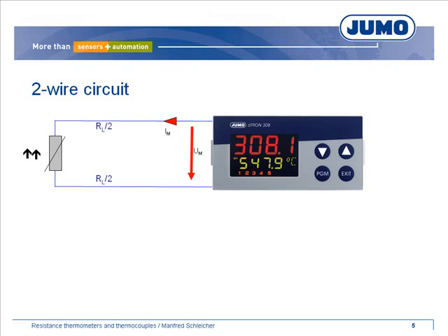Resistance thermometers can be connected to a field device in 3 different circuit versions. The picture shows the so-called 2-wire circuit. In that case, the field device measures the resistance value of the thermometer plus the lead resistance. A higher temperature than the real temperature on the resistance thermometer is measured. The offset can be corrected in the device or with the help of the setup program.